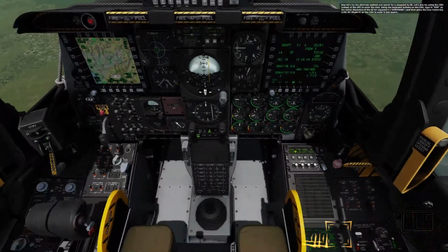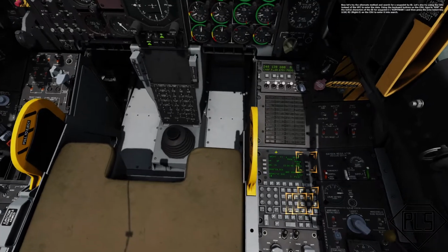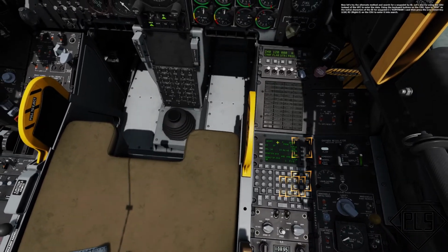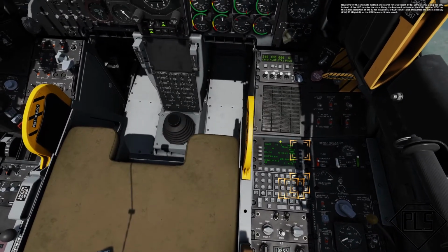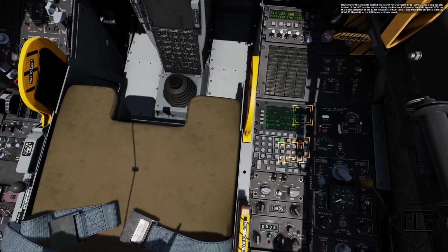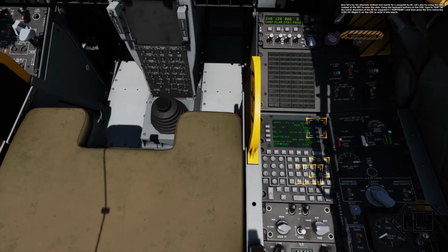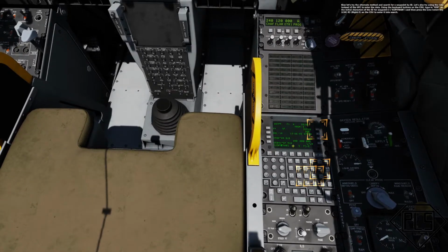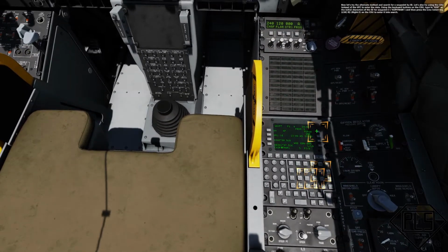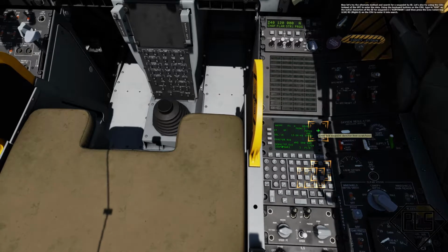Now let's try the alternate method and search for a waypoint by ID. Let's also try using the CDU instead of the UFC to enter the data. Using the keyboard buttons on the CDU, type in KOP as the initial characters of the ID for waypoint 3, Kopignati, and then press the line select key R3 on the CDU to enter it into search.